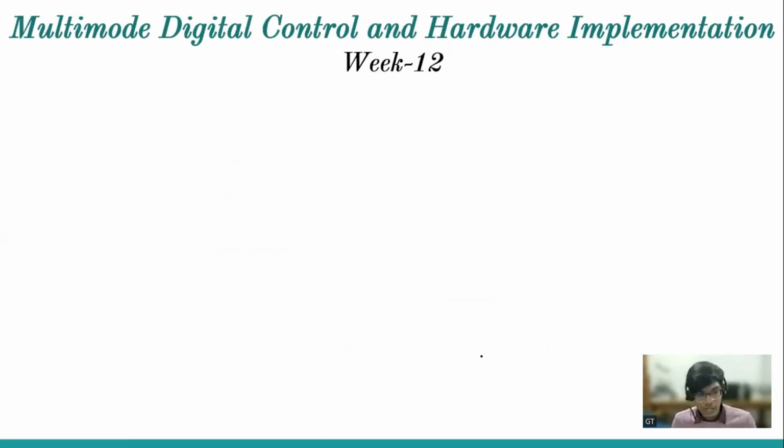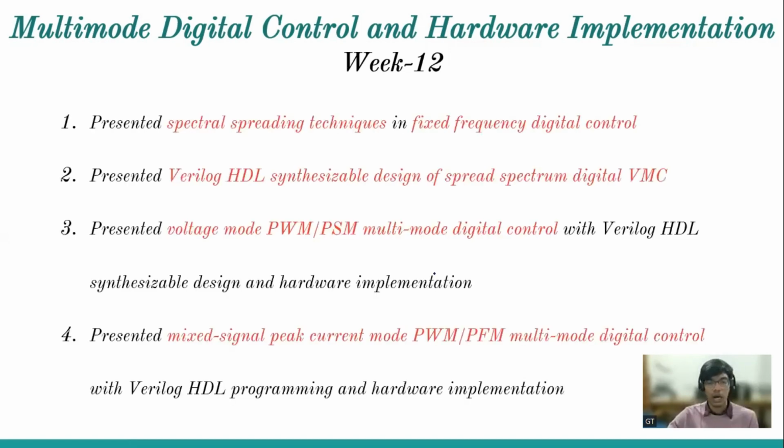Coming to week 12, which is the last week, the final week of this course, which we discussed recently: the multi-mode digital control and hardware implementation. So why is multi-mode needed? It has one light load control technique plus one full load or high load technique. At light load, it is operating in one control architecture, and at high load it is shifting to the other.